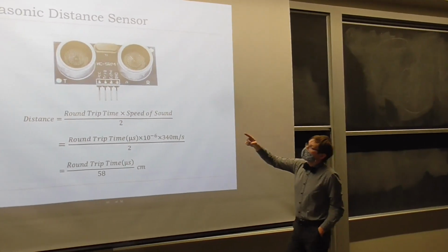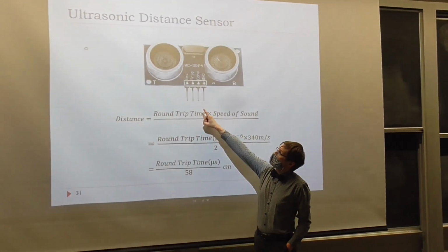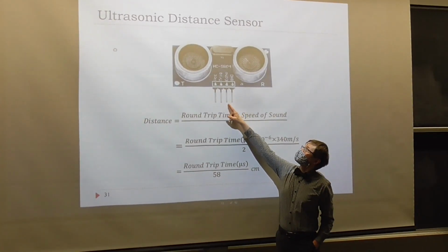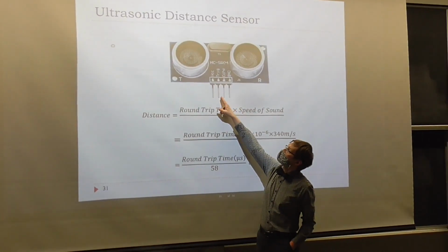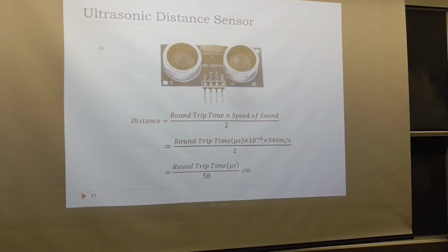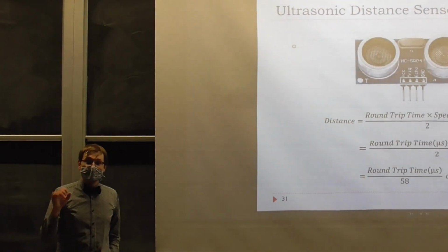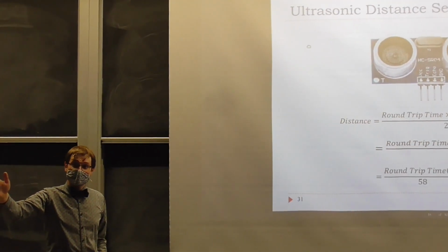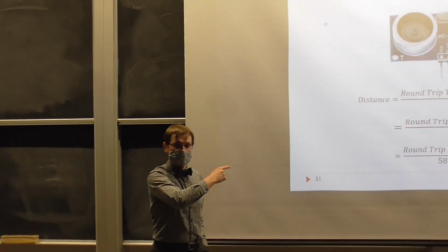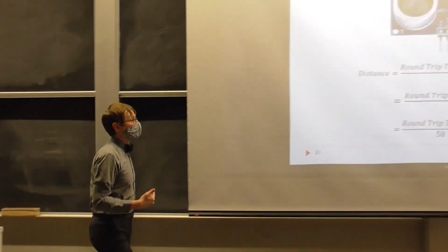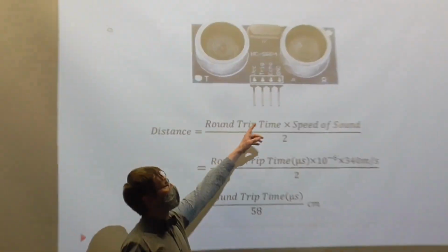So with this, you've got 2 pins here which are important, right? You've got ground and VCC obviously, but you've also got a trigger line and an echo line. When the ultrasonic sensor sends out a pulse, it also sends out an electronic signal over the trigger pin. When it receives the echo back, it sends an electronic pulse out of the echo pin.